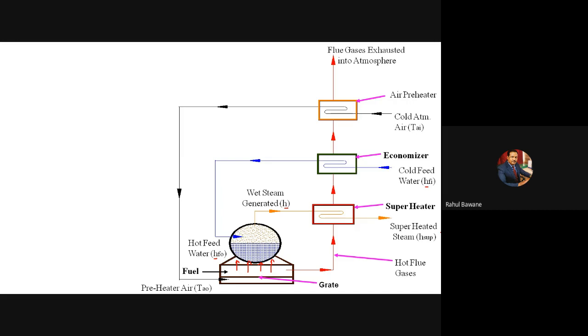After that, if we provide heat, the steam at 100 degree centigrade gets superheated. Steam temperature rises, so we get 110, 120 degree centigrade steam. That means we get superheated steam, which has its own enthalpy, denoted by H super, that is, of superheated steam.